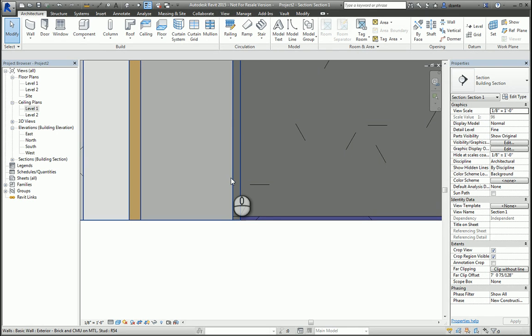If you don't have a base and you just want that chipboard to be constructed all the way down to the floor and have the tile go and meet up against it and basically hide that really bad edge of that cut of the chipboard, then you would want the edge of the floor to be at this line, not this line. So just little things like that to think about when you're putting in a floor.